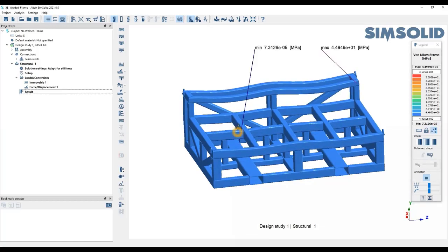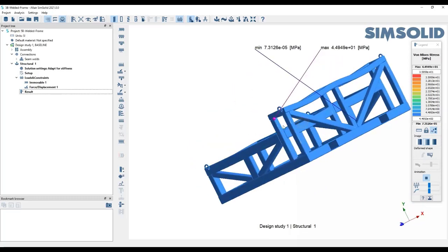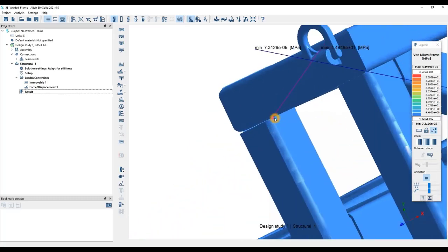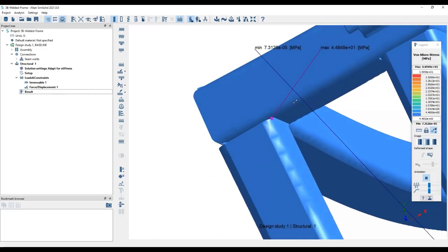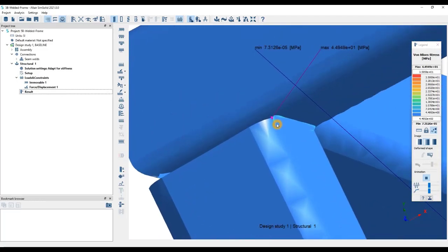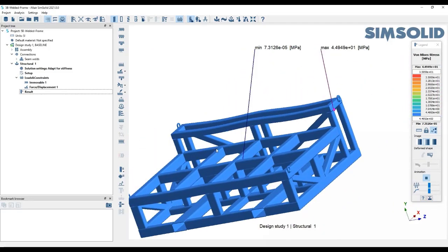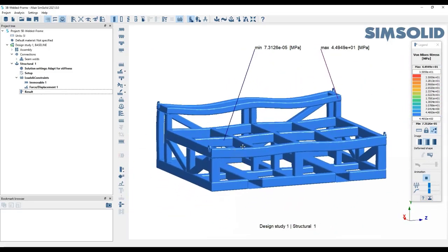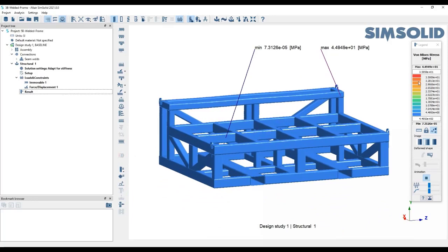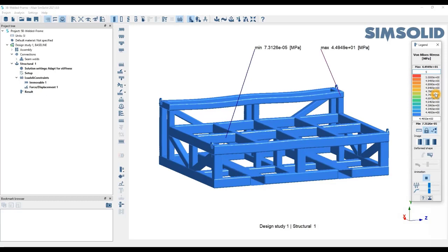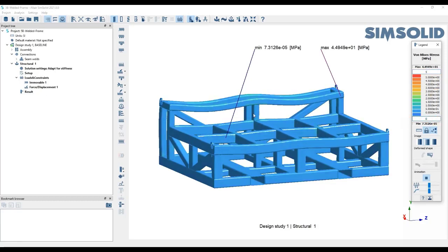We can click on the min-max values, and you can see that the maximum stress occurring right now is actually at the back part here, acting upon a weld in itself. And say if you wanted to dramatize your contour plots, you can always adjust these accordingly. So let's make this 5, and let's make this one 0. So you can see which areas undergo most stresses.